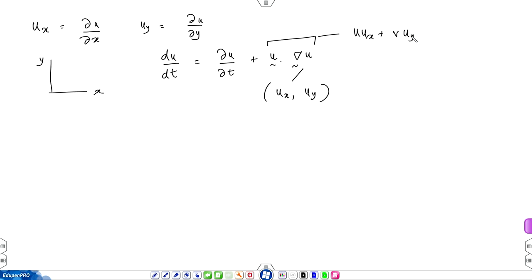How about the right hand side? The right hand side, yes, because your frame of reference is fixed. What is the meaning of del u del x, partial derivative of u with x? That means you put the frame of reference there, and it's just u at the neighborhood point minus u at the original point divided by delta x, and there is no reference to the flow direction. There is only reference to a coordinate system which is with you.